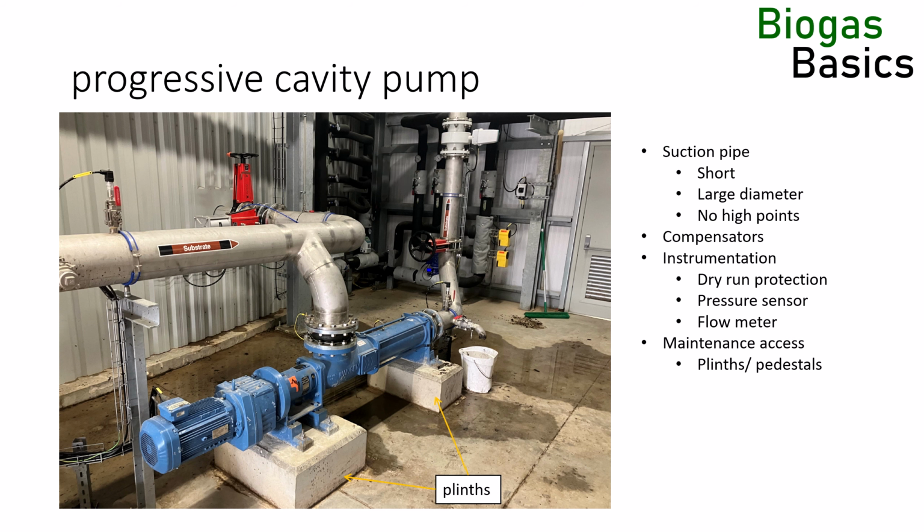It is recommended to install the pump onto a plinth or pedestal, so it is possible to put a pallet truck under it.